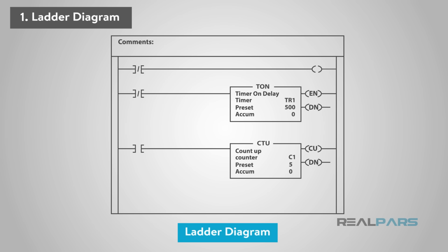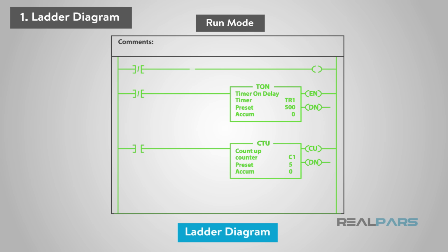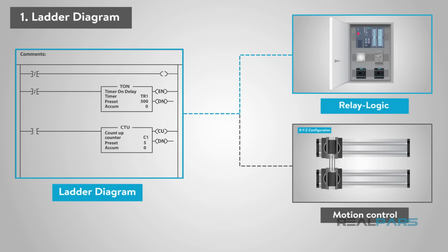The main advantages of the Ladder Diagram language are that the rungs allow it to be organized and easy to follow. It also lets you document comments that are readily visible, and it supports online editing very successfully. The main disadvantage is that there are some instructions that are not available, which might make it more difficult for programming, such as motion or batching.